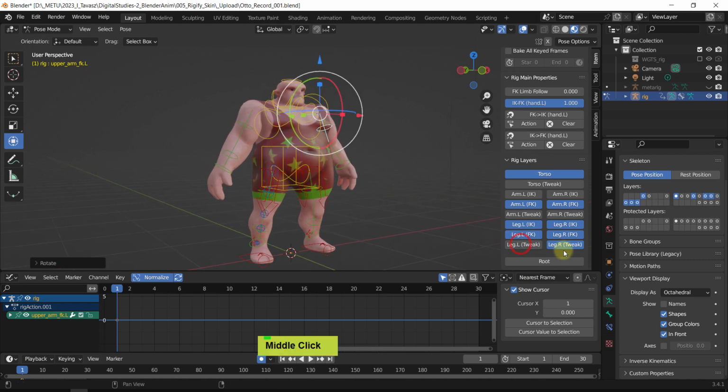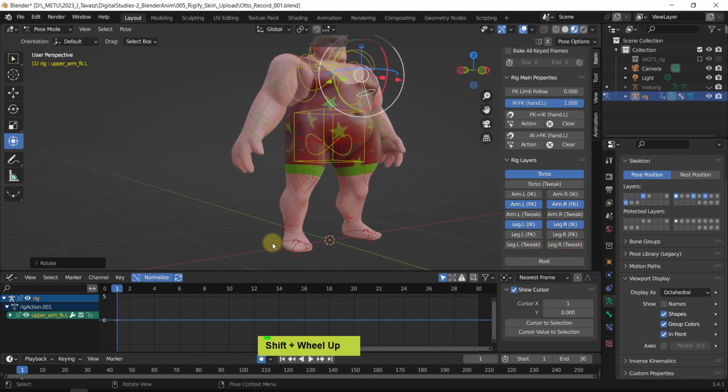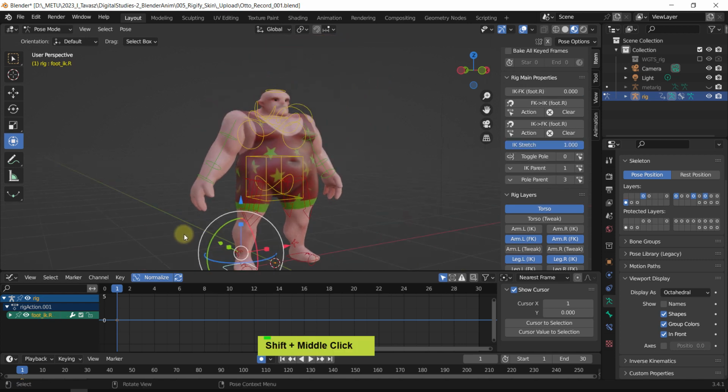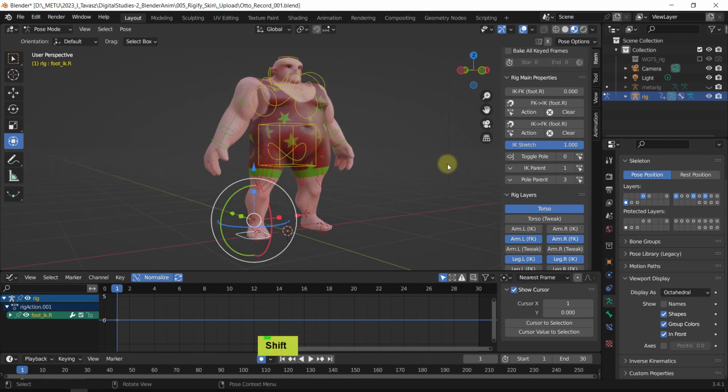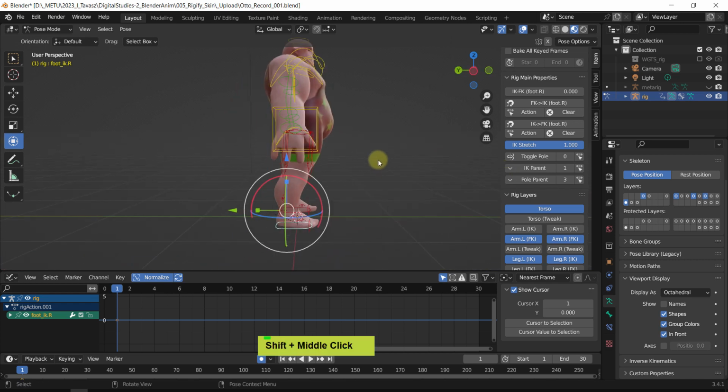And we don't need any tweaks for the bones, and we need no FKs in this case because IK will be used. Again, we are using an IK system to create the walk. Yes, in some cases you want to switch between IK and FK when you are creating a walk, but this will be a simple one. We don't have to animate too much when the feet are in the air. Okay, now let's start with the first thing.